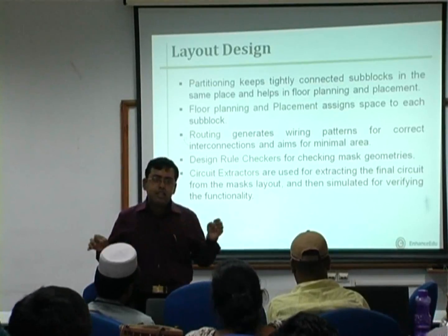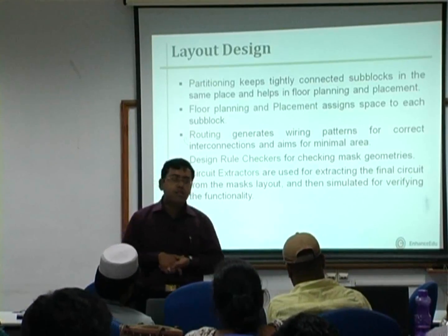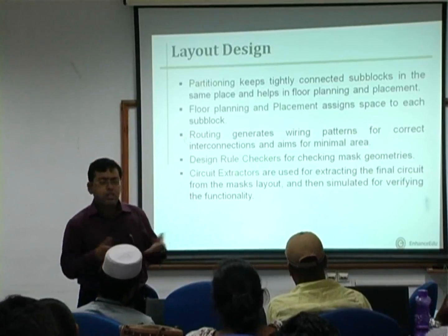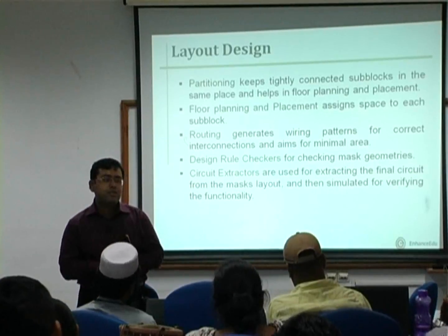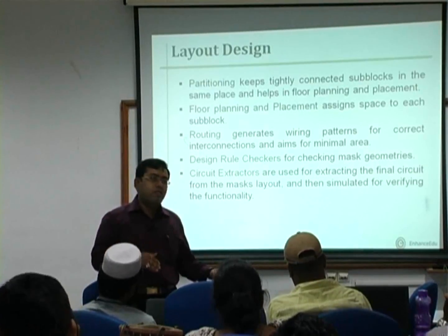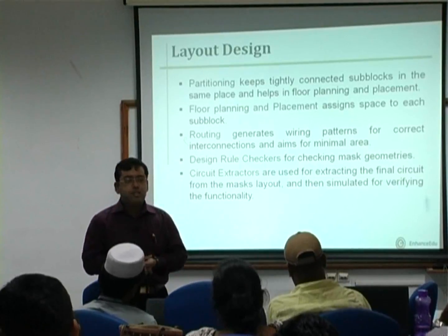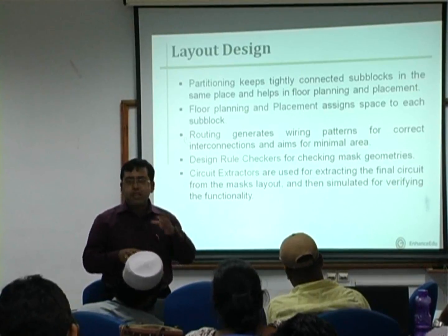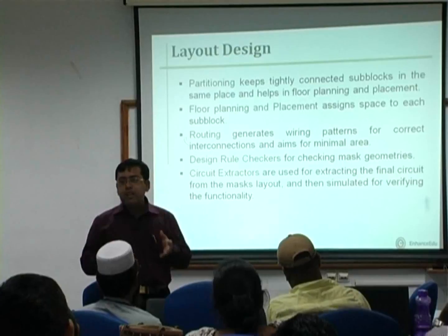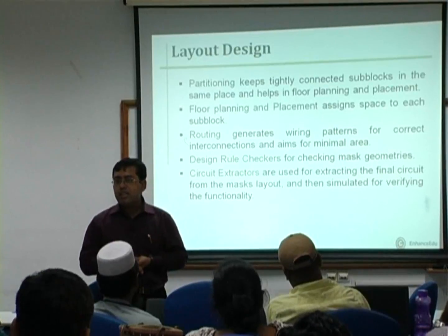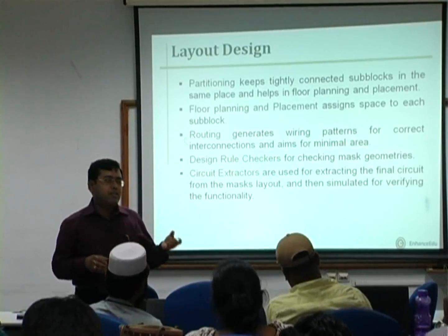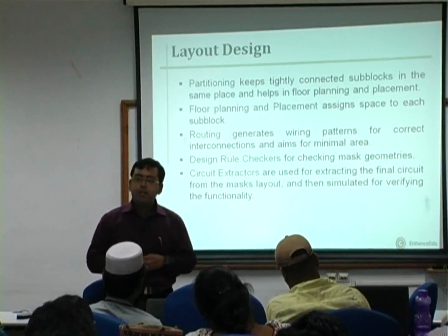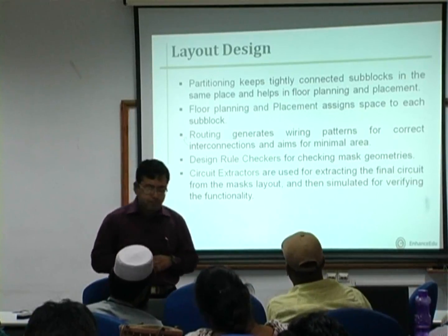And then you define the interconnections amongst the different components in the routing phase, which again spans two subphases, like global routing and detailed routing. In the global routing phase you define the approximate pathways of the interconnects, and in the detailed routing phase you exactly define the pathways of the interconnects.